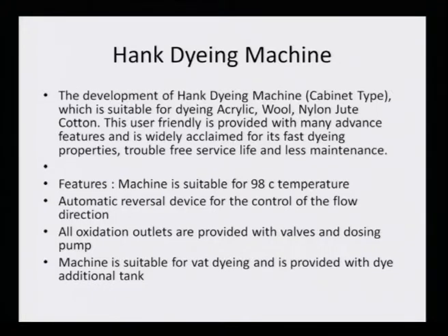So, you see, we were talking about vat dyeing. Now, here is a machine that can actually do the vat dyeing without using the vat, and hang dyeing can do that. It has that kind of equipment where no oxidation will occur while the dyeing is taking place, because we just learned about vat dyeing, and that is precisely why I took the vat dyeing before this lecture, because I wanted you to understand that there is a machine on an industrial scale. Hang dyeing machines can be used for vat dyeing. So, one need not necessarily have a vat to do the vat dyeing. That was the initial or the historic way of doing it, but now hang dyeing machines can do vat dyeing very easily.